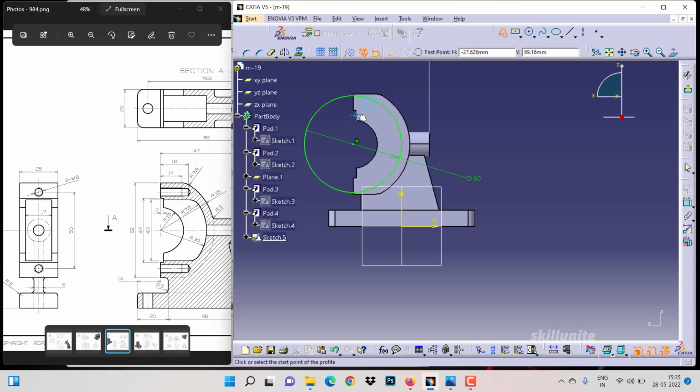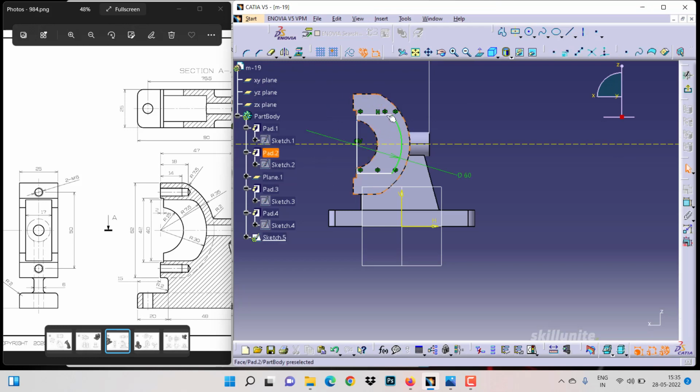From your connector, straight line. Then maybe what you can do, you can mirror this one with respect to the center, so that is fine. Automatically the object got mirrored. On this side, simply close it like this. The extras, whatever it is there, trim it out. Now as you can notice, this is at 40 mm from the middle.